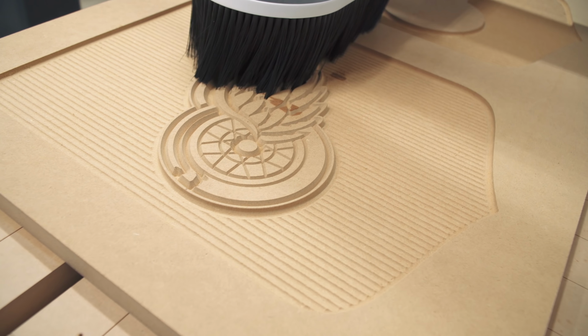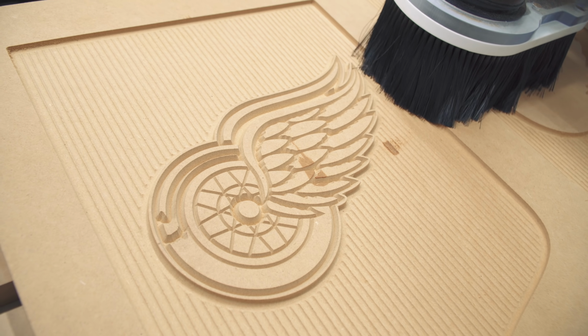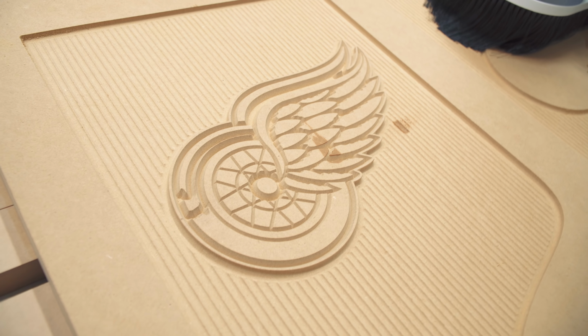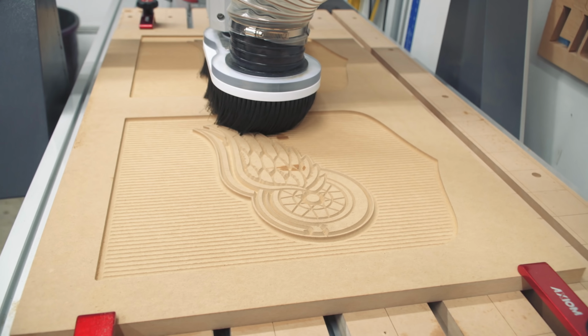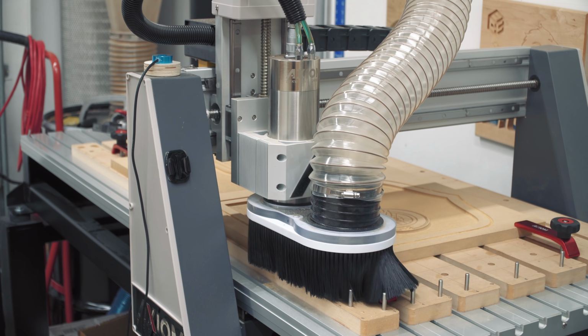MDF cuts really good. Now, remember that I created a pocket clearance toolpath with the end mill, but I started these V-carve toolpaths with the V-bit first before the end mill toolpath, just because I get better results when doing so. Finally, the 1/4 inch end mill is used to finish the logo and establish the sign perimeter.